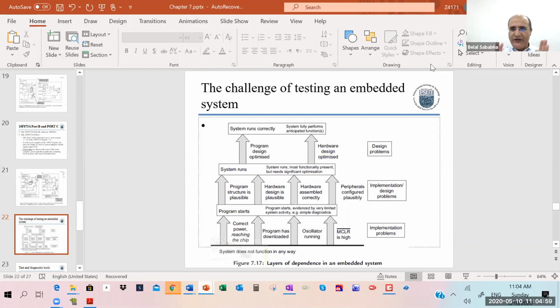So to summarize, the new things in the 77A controller are the program memory, which now has pages. We did not have this concept before. The data memory now has 4 banks, and we only had 2 in the previous one. Here we have more interrupts, and a new concept called peripheral interrupt enable is introduced. We are dealing with 15 interrupt sources versus the 4 in the 16F84A controller. And the last thing is the ports. We used to have 2 ports, port A and B. Now we have 5 ports, A, B, C, D, and E. Okay?